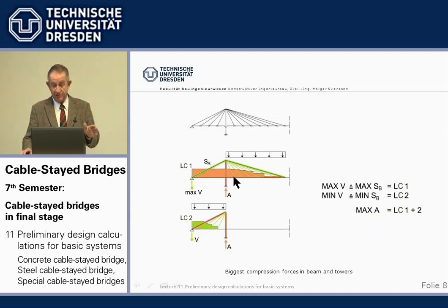The dead load arrangement and distribution is a special topic we will come to. The live load is very easy. We have basically two live load cases. One, full loading of the main span, and the other one is full loading of the side span.